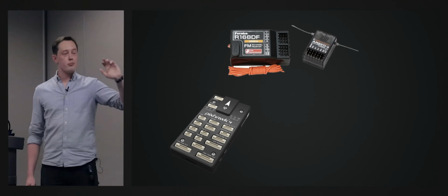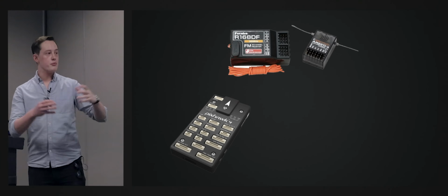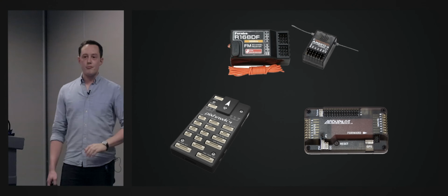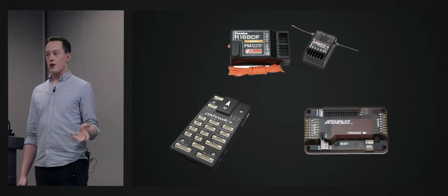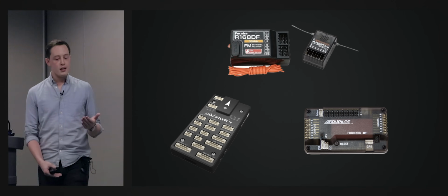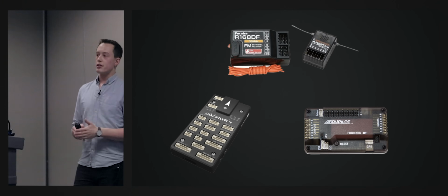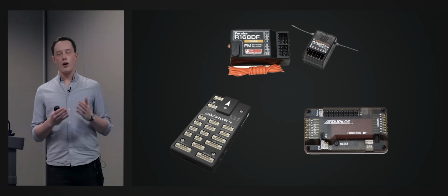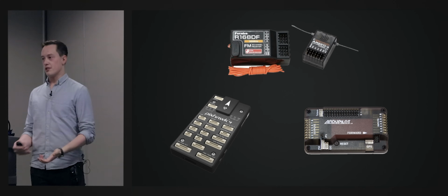You could have a Pixhawk. These are sort of all-in-one flight control systems. You can also have an ArduPilot, APM. All of these are cool options for model airplanes, but I don't recommend using them for model rockets. What you really want to have is full control over the software that's running on it and full control over the hardware that's going on it. And that's going to be the most efficient approach.